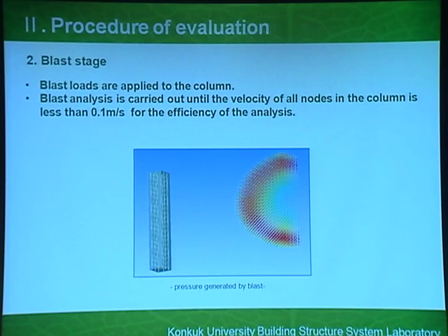For the efficiency of analysis, we cut off our calculation and set up some criteria. That is, if all of the nodes have a velocity of less than 0.1 meter per second, then we assume the actual dynamic response is terminated, so we terminate our analysis.